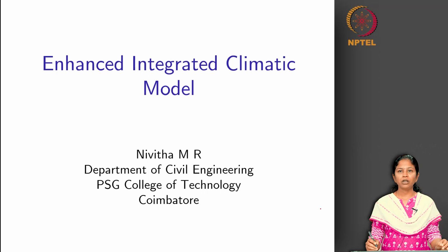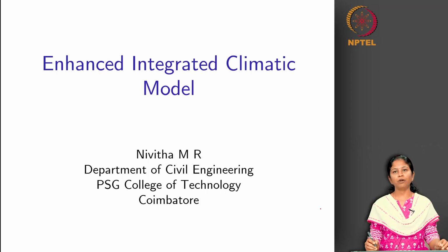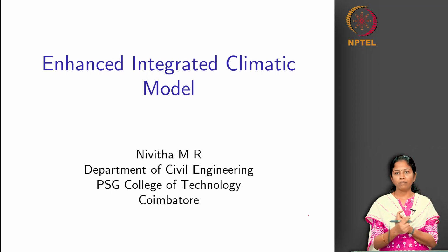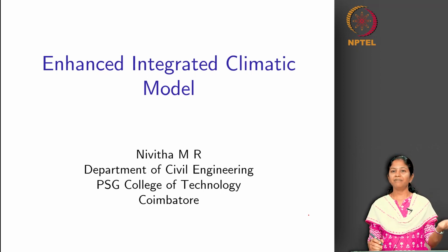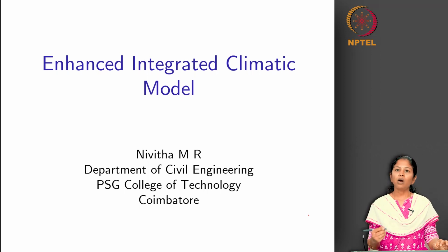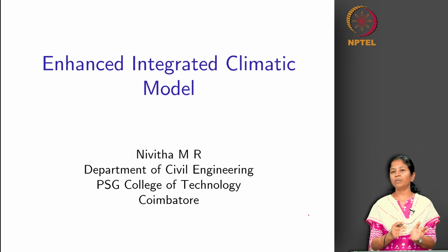So far, we have been talking about different influences of environmental factors on the design input parameters, primarily the modulus. We had seen how moisture affects the subgrade modulus, how moisture affects freeze and thaw in the pavement, how the temperature profile affects the modulus value of the bituminous layers, and how it contributes again to freeze and thaw in the pavement. All these effects we had seen, and we had also seen the sensitivity of modulus to all these parameters. Now, how do we incorporate that into the design procedure?